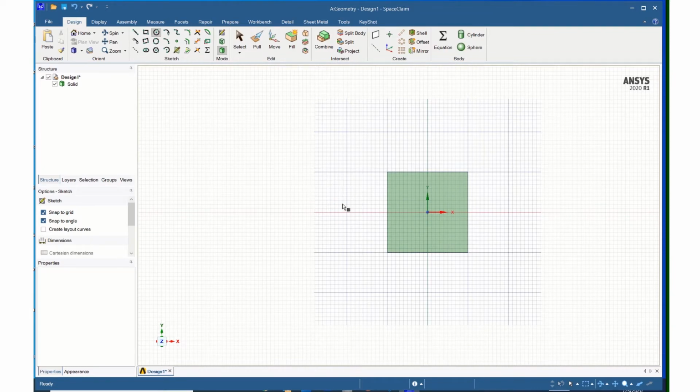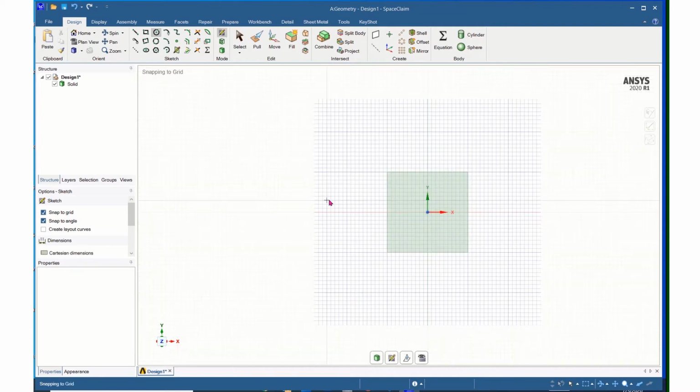I see that I have crosshatches on my cursor and I don't have the square to draw a circle, so I actually need to select this sketch plane, and now I have the crosshatch on my circle tool that I can use to select and build my circle. I'll come down 3 units from the top and click and drag out a 4 millimeter circle, so 4, enter.